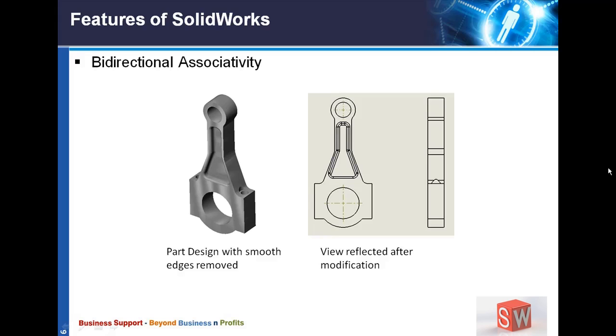Once he has designed and goes on to create the orthographic views, there is a small feedback from the assembly department saying that all the sharp corners have to be blended, so that they will not damage the users. If he wants to modify the sharp edges, he will blend them using a command called round.